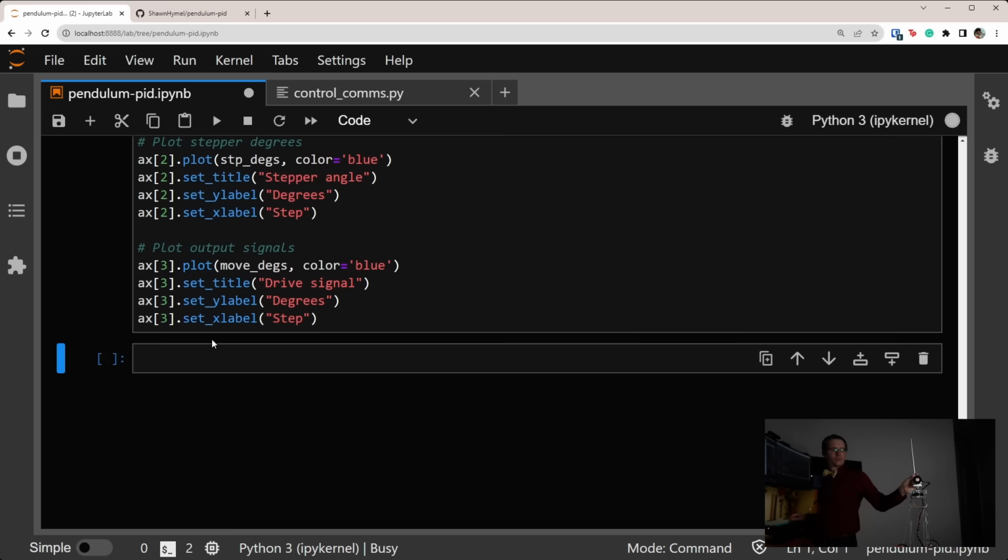Now we can take some time and really tune these, but I think with a Kp of 0.3 and a Ki of 0.005, it's gonna be good enough for now and our demonstration. As you can see, this PI controller pretty much does the job for us. We probably don't even need a derivative term in here, but let's just play with it and see what happens.